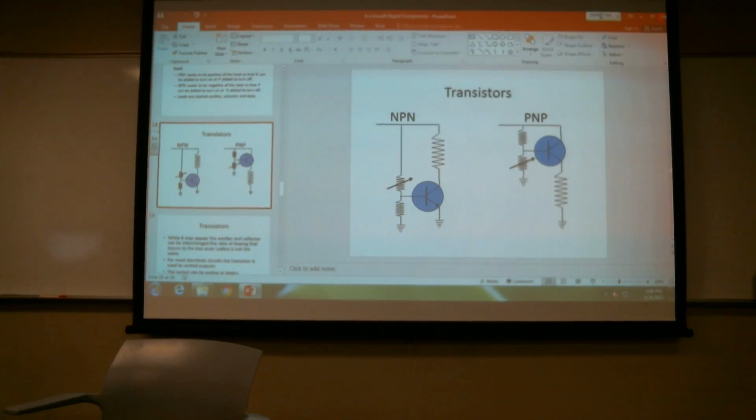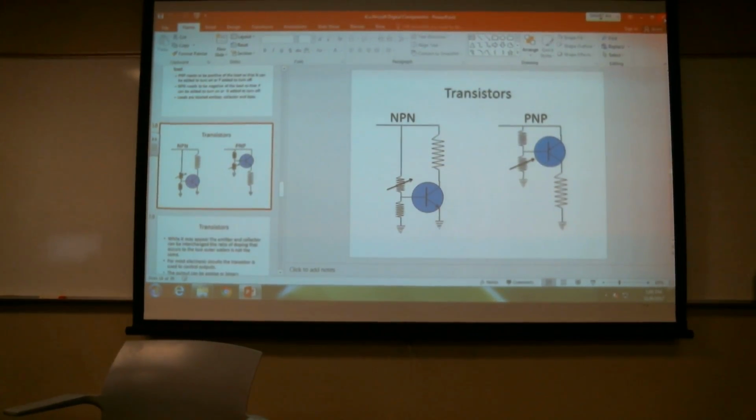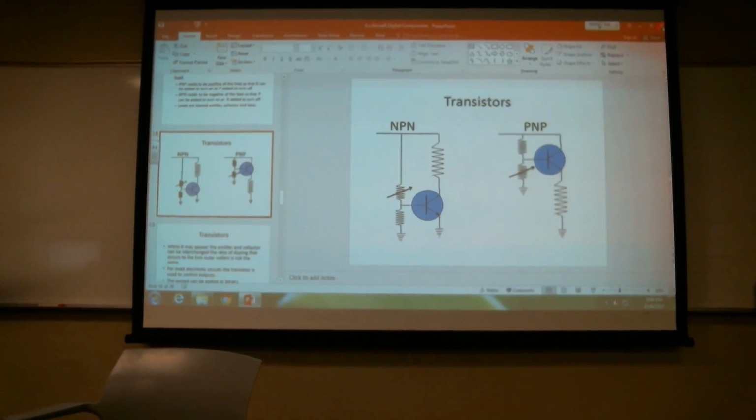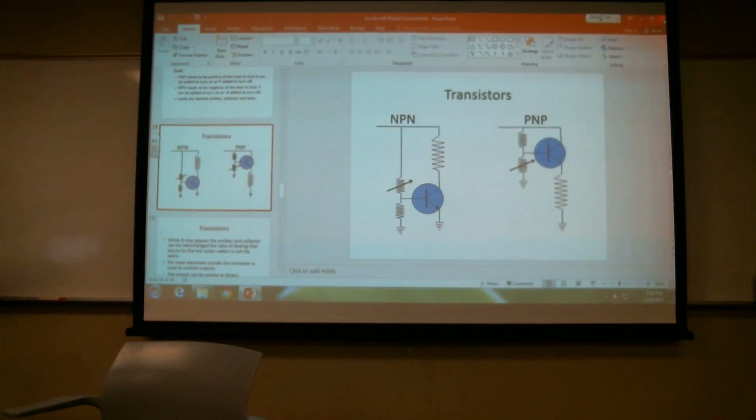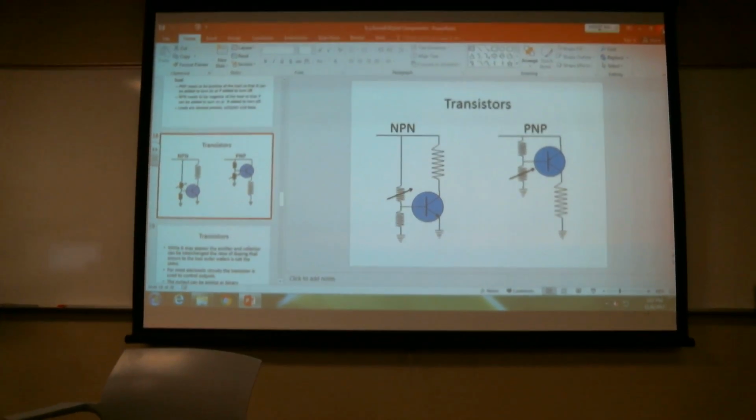The whole purpose of the other side of the voltage divider is just to ensure it truly does shut off. We often use transistors because it uses so much less current as a switching device versus an analog device. If the load was an audio speaker, it's purely analog, and that transistor is going to get really, really hot because it's going to be acting like a big variable resistor. So it's going to need a really big heat sink.